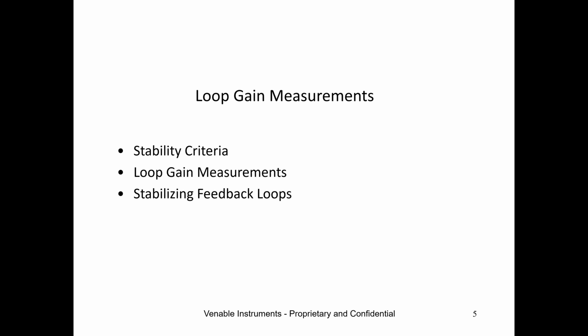Okay. Well, we are using a method developed by Dr. Middlebrook on how to measure a loop, open loop gain with the loop closed. So that's how we do it. It makes it a lot easier. You don't have to bias up the loop. You can just connect our injection generator in series with the loop.